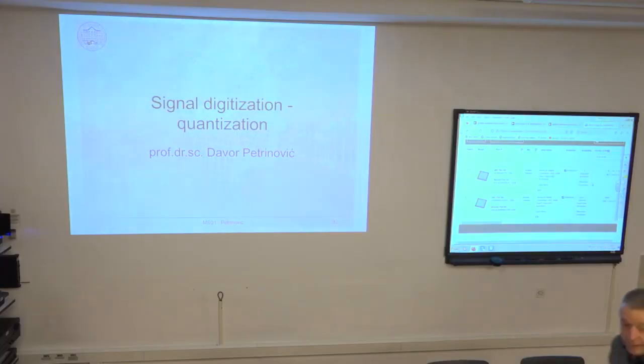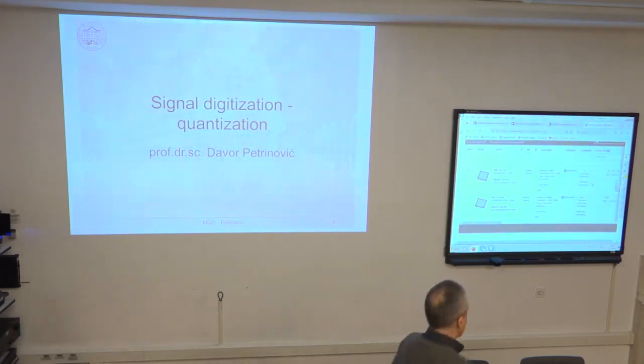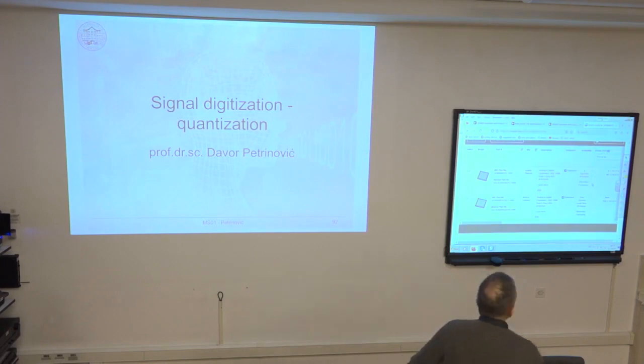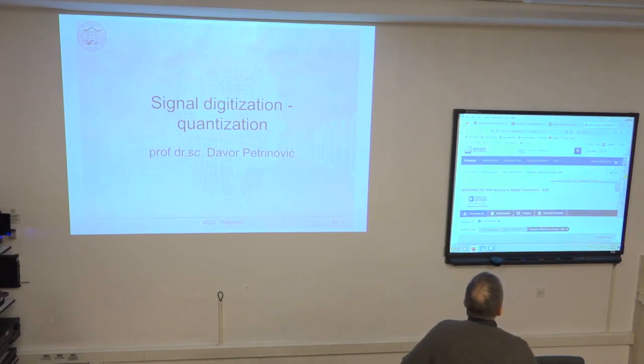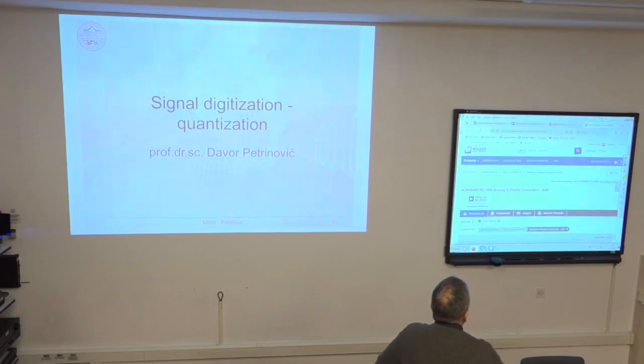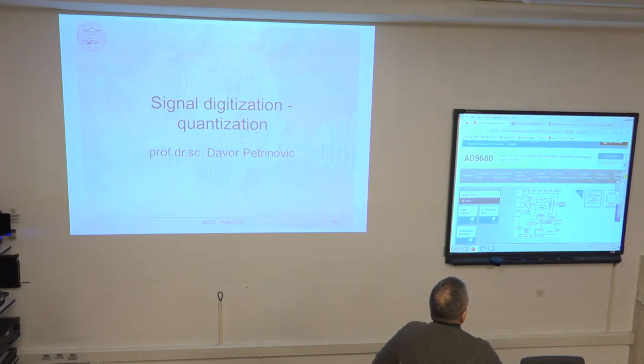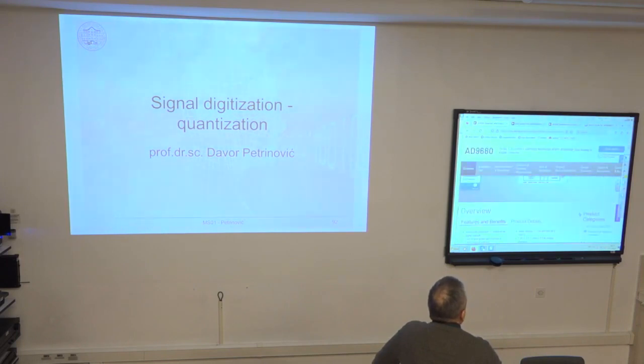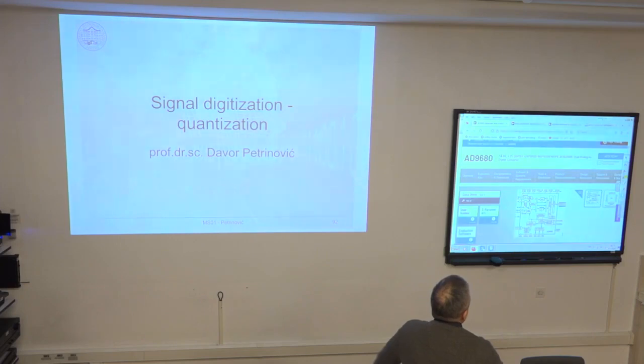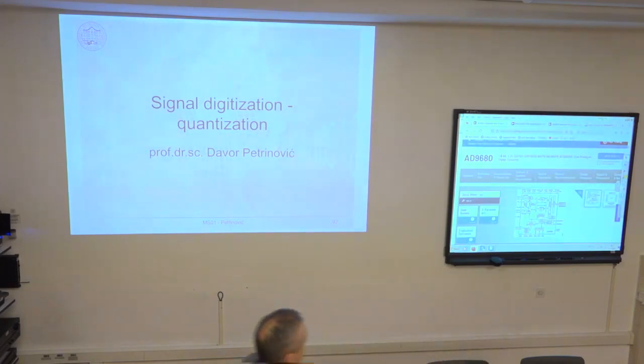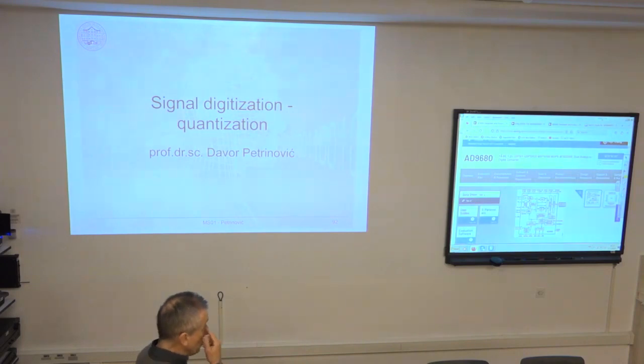I have opened here one example of a modern AD converter from the company Analog Devices. It is maybe most famous for AD conversion. For example, they produce the AD9680, and if you go to the product brief, it says it is a 14-bit, 1.25 gigasample per second converter.